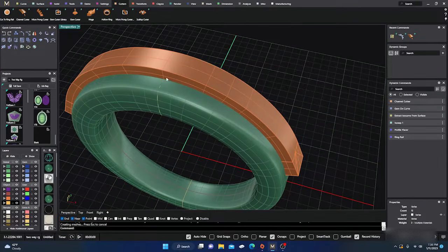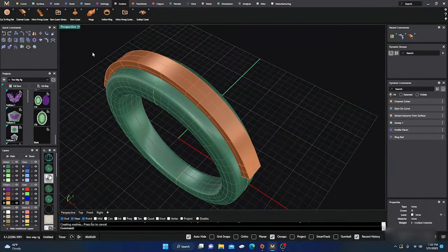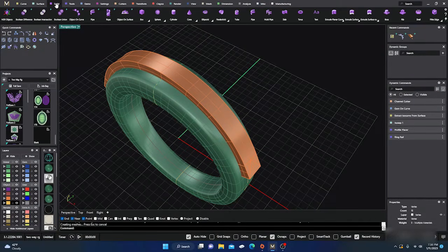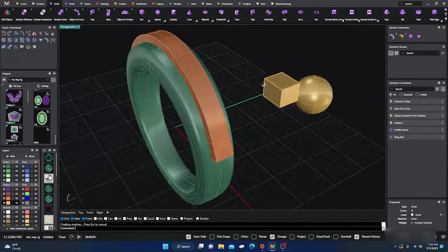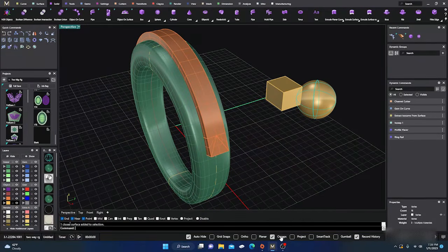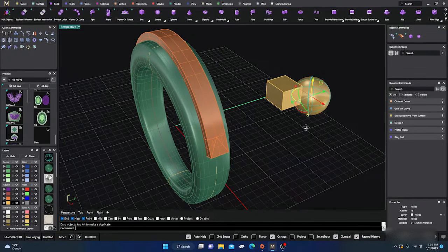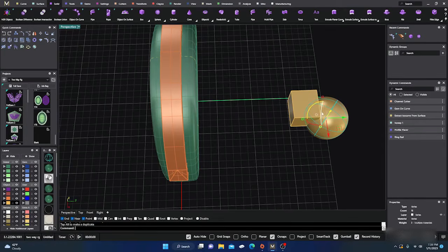Now we need to cut that surface, right? So what we need to do is we go to our solids menu, and right here is a boolean. Boolean difference will cut away. Boolean union will take the two items and, like here very quickly, I'll grab a box. I'll just draw a box here, and I'll grab a circle, and we'll draw a circle right here. And you can see, oh, my gumball's not on. I'm going to turn my gumball on for easy movement, and they're intersecting, right?